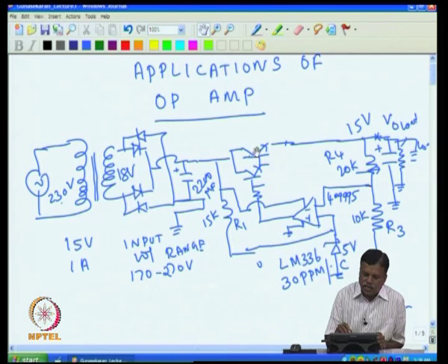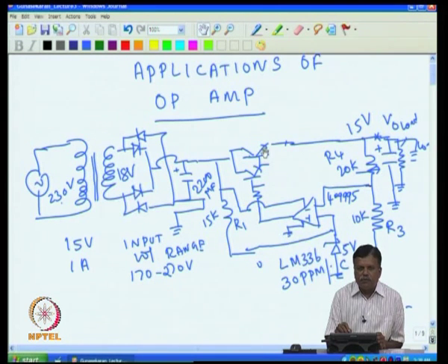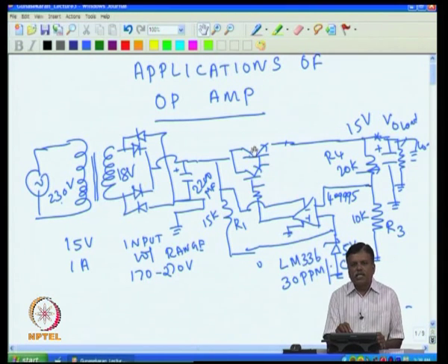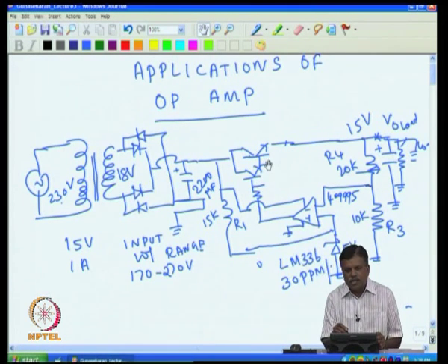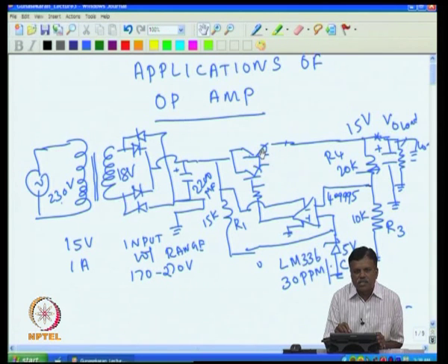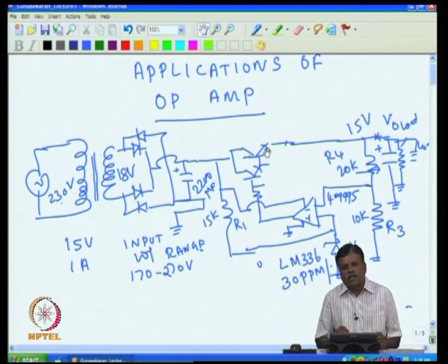So, I should never attempt to operate this at 150 degree. In that case, the life will be less. For example, if you design this transistor such that every time when switch on, the temperature of the junction goes 150 degree, then probably if you are using it in a TV, in 3 months time your TV had to go for servicing because this transistor would have blown up. Because this transistor, the voltage regulator decides the life of the equipment very critically.